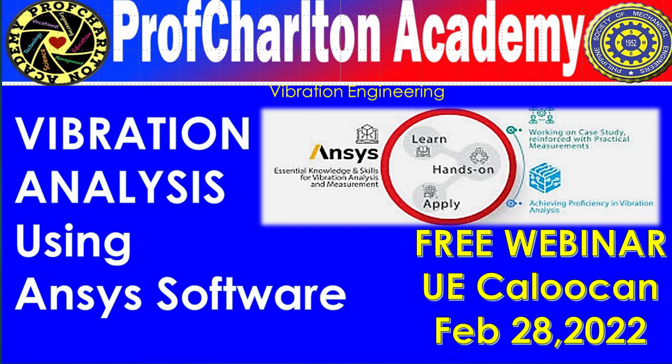We have a lot of pre-processing tools for additive print, because in additive manufacturing, support generation is also one of the important tasks. So we have an additive prep module which helps you to prepare your model for printing. You can convert to STL and fix issues with your STL models, prepare the support, do part nesting, and set the right orientations. All this can be done using additive prep.